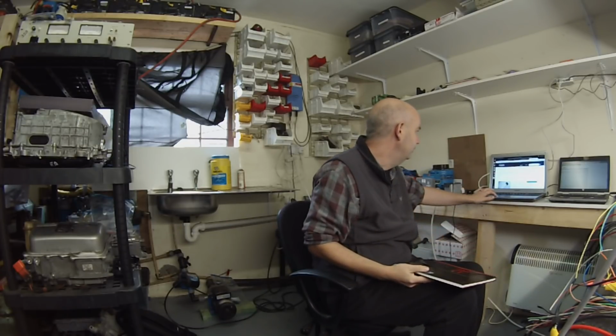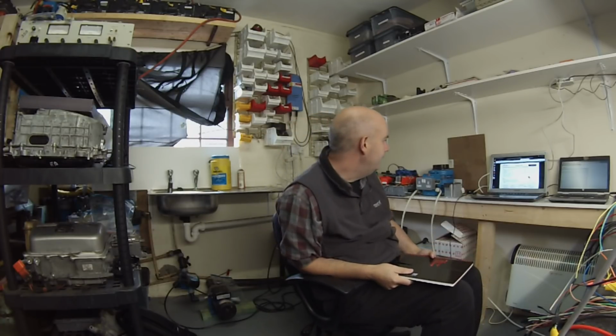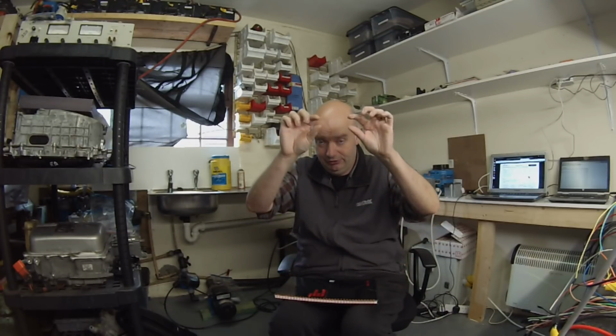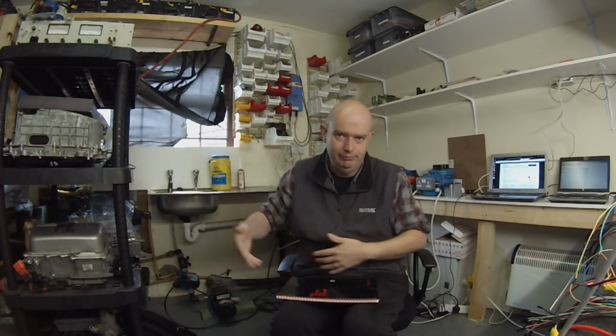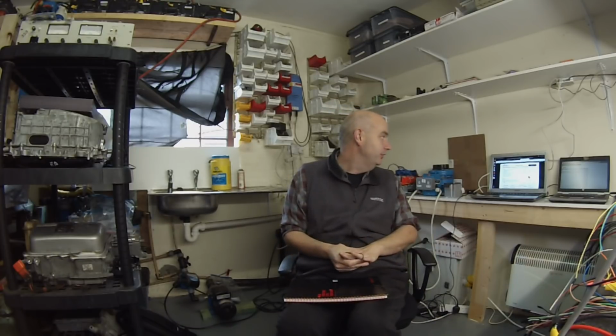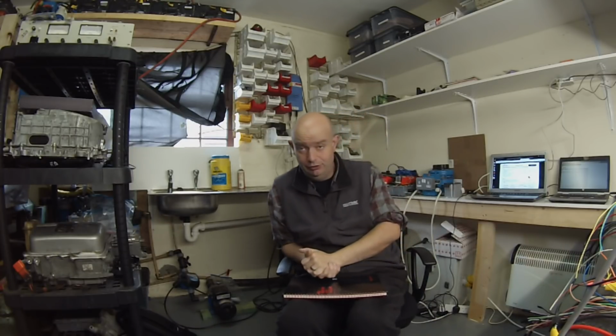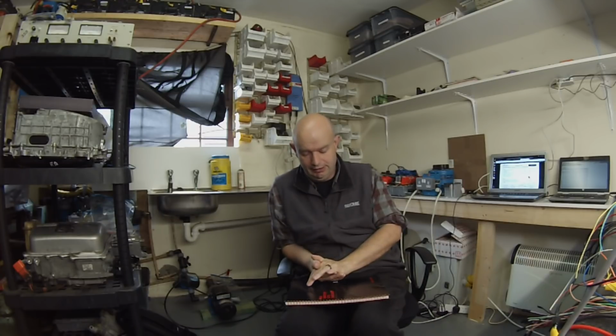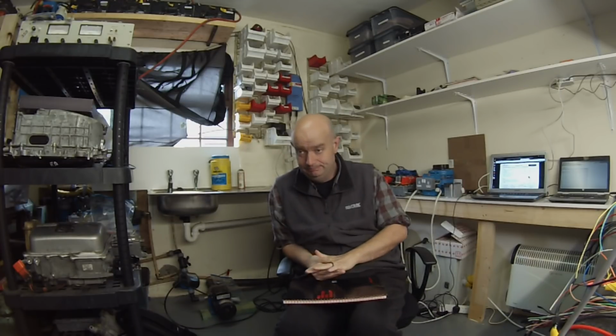So the part number for the IGBT is the AUIRGPS4067D1. And there are 6 of them per switch. So there's 6 on the high side, 6 on the low side, times 3, right? So there's 6 transistors connected in parallel on each switch. And they have a nominal current rating of 120 amps according to the data sheet.